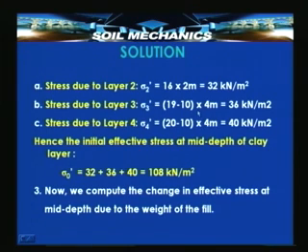So, 19 minus 10 into 4, that is 36 kilonewton per meter square, and that is the stress that arises at the mid depth of the clay layer due to the weight or the self weight of the lower part of the sand layer. Now, in this we have made one small assumption, which although mentioned in the slide, I had not elaborated upon.